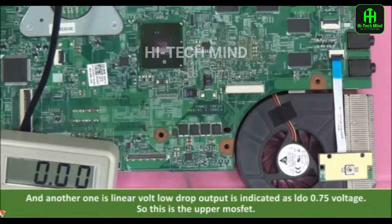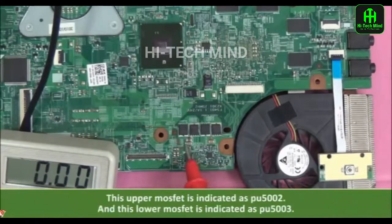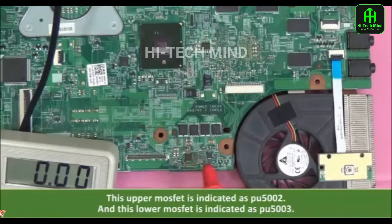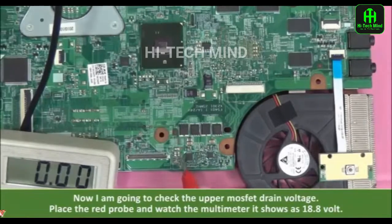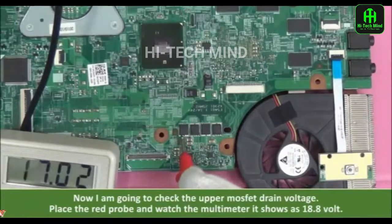So this is the upper MOSFET. This upper MOSFET is indicated as PU5002 and this lower side MOSFET is indicated as PU5003. Now I am going to check the upper MOSFET drain voltage. Place the red probe and watch the multimeter. It shows 18.8 volt.